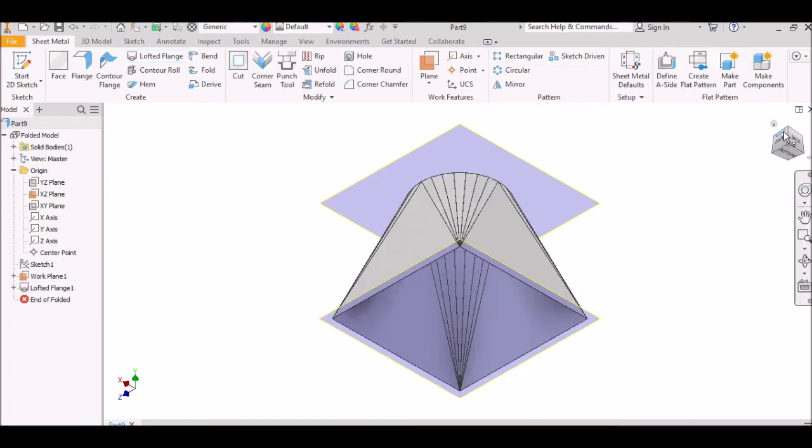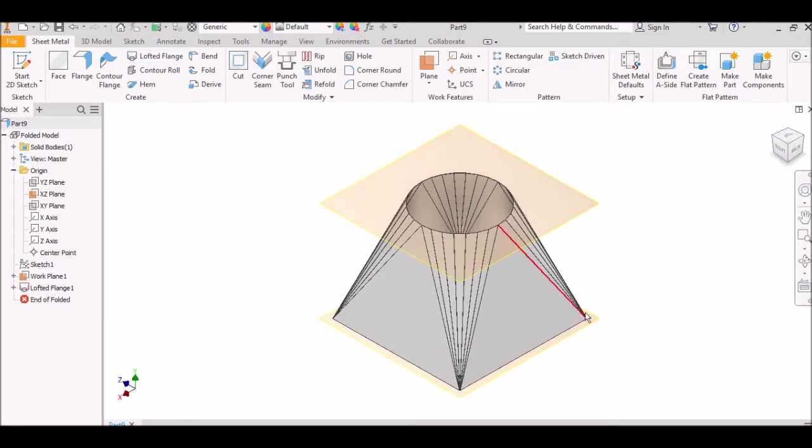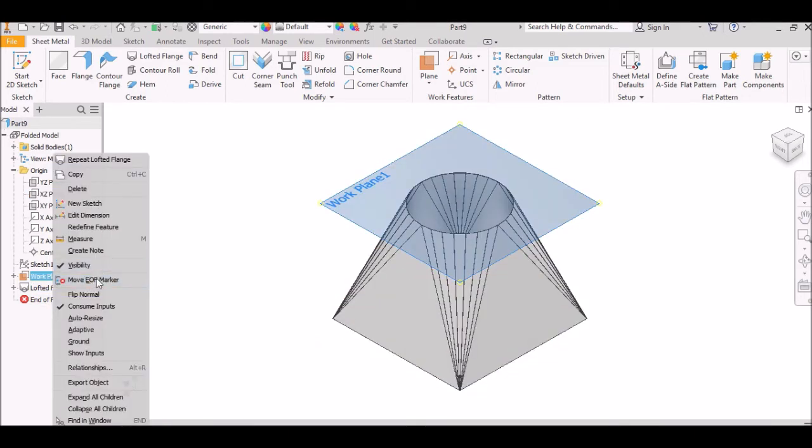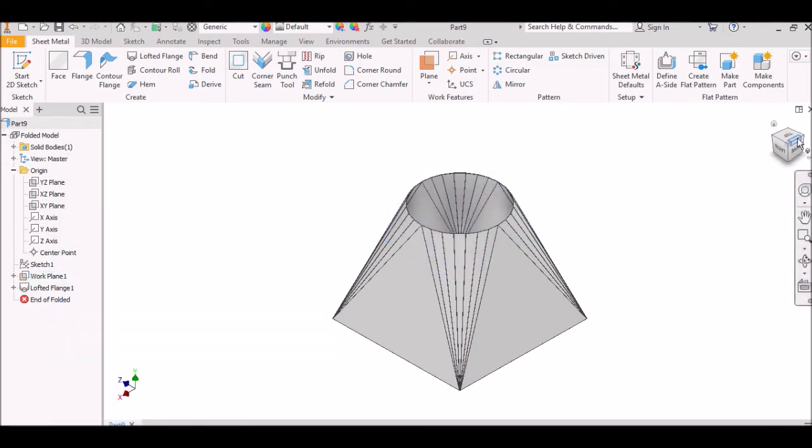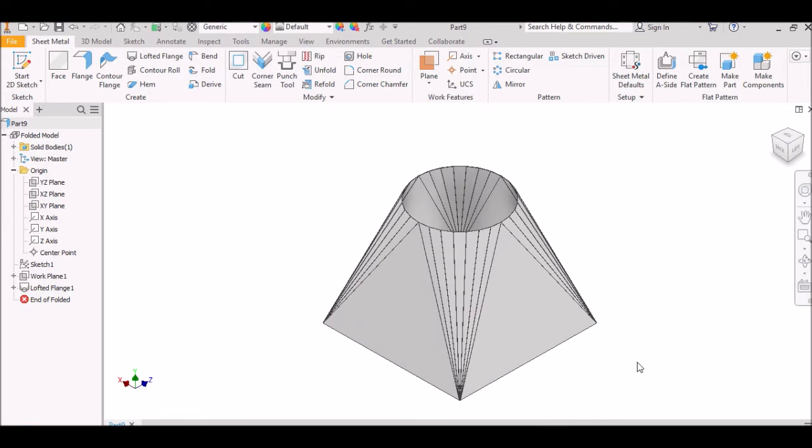Now it's important at this point that you remember that these sizes that we've put in can be changed to anything you want really. You have to be a little bit careful so that you don't make it too small, because otherwise your flange won't work. But we can make the bottom 400 millimeters, the top 200 millimeters, the bottom a meter wide, the top whatever we want. So we can adjust these sizes to whatever system we're working on.